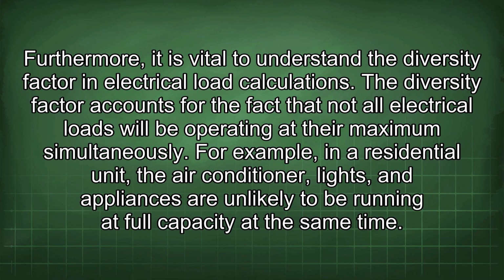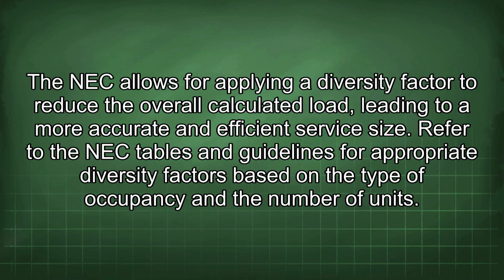Furthermore, it is vital to understand the diversity factor in electrical load calculations. The diversity factor accounts for the fact that not all electrical loads will be operating at their maximum simultaneously. For example, in a residential unit, the air conditioner, lights, and appliances are unlikely to be running at full capacity at the same time. The NEC allows for applying a diversity factor to reduce the overall calculated load, leading to a more accurate and efficient service size.